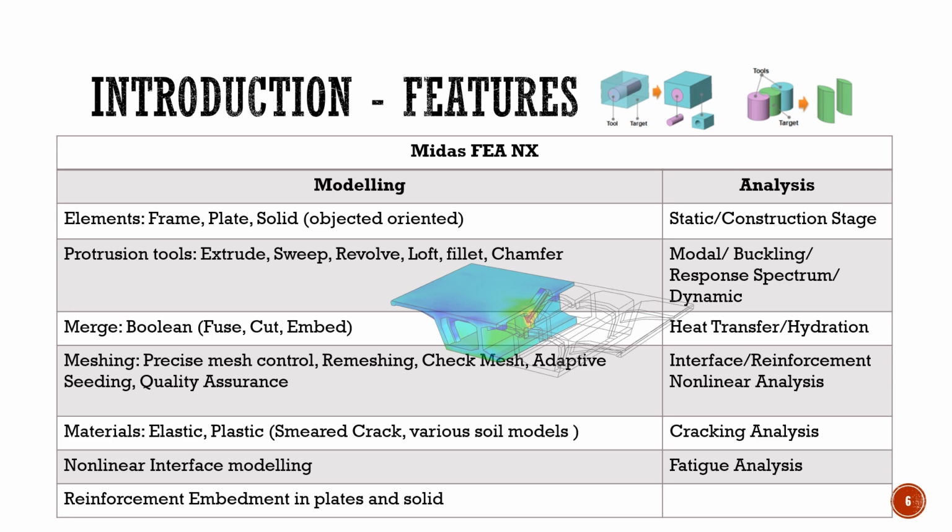Moreover, it supports nonlinear interface modeling for the simulation of bond slip, steel concrete interface, bolted connection interface, etc. Also, the embedment of rebar and tendons in plates and solids can be achieved, which is useful for the modeling of blisters as an example.